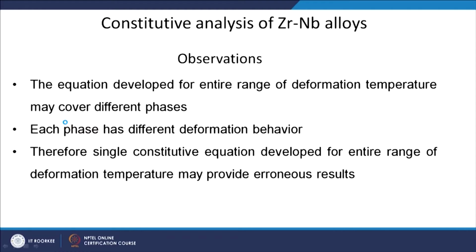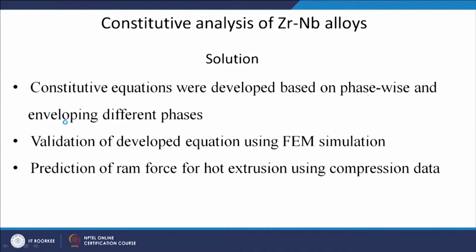When we use this constitutive equation for modeling, the modeling will not be able to give you accurate output, that is what we felt. So, the solution we provided is that the constitutive equation should be developed as a function of phase. That means different phase regions should have different constitutive equations.